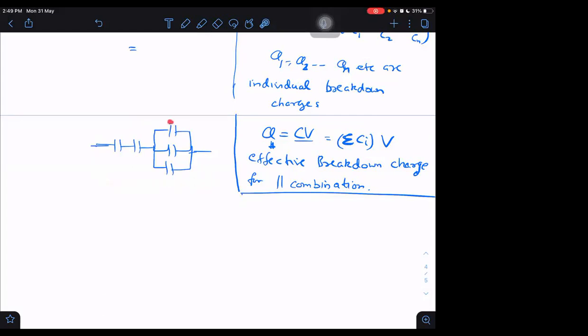first of all, the question can be that there are capacitors and I have to arrange them according to my own choice. Then I will prefer to arrange them in series. Then I can apply the maximum possible voltage. But if they are already fixing the arrangement and then asking what's the maximum safe voltage you can apply, then solve these separately first, the parallel parts and then the series. Find out what is the maximum safe voltage for this.